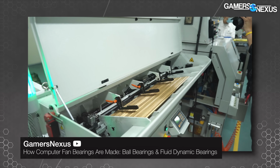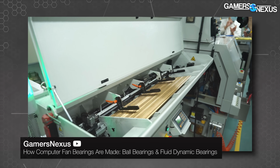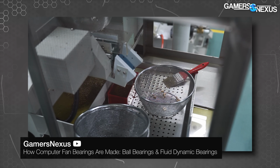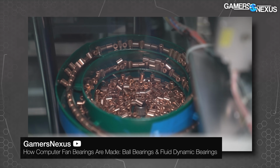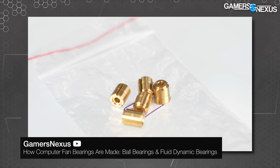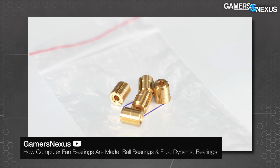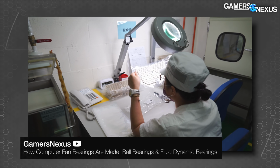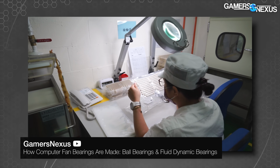It's pretty similar to heat pipes, where on paper it looks so obvious that, let's say, composite heat pipes are superior to regular sinter type heat pipes. But we briefly spoke about this last year. I think a good regular sintered heat pipe outperforms a badly done composite one any day. And it's the same with bearings. You may have the biggest herringbone structure ever, but it could still be an utterly poor bearing. So this basic structure won't give you any information regarding whether it's a good bearing or not.